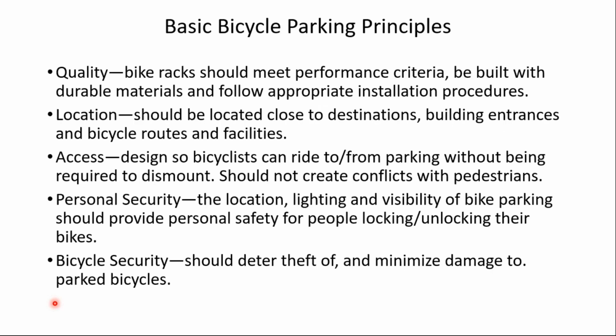Some of the basic bike parking principles: quality equipment or devices. The bike racks should meet some performance criteria, and should be located next to or close to destinations, building entrances, bike routes. Designed so that the bicyclist can ride to or from the parking without having to dismount, and should try to minimize conflicts with pedestrians.